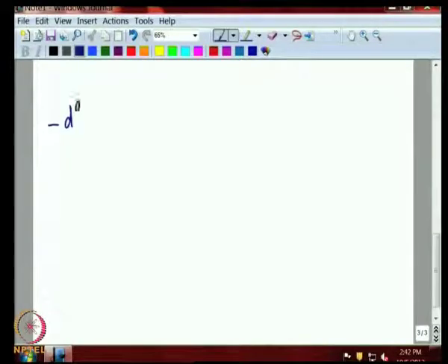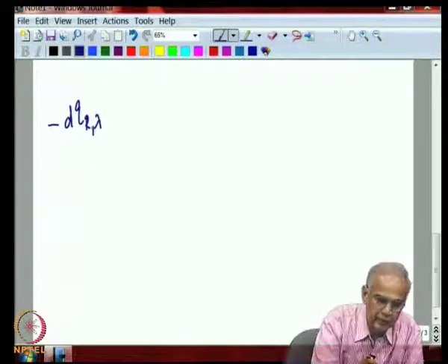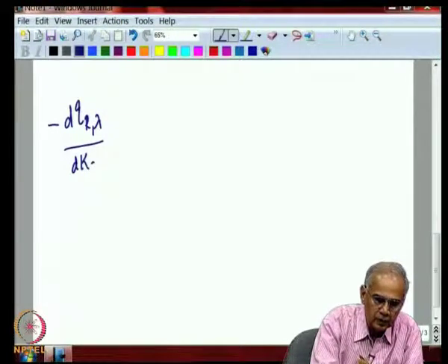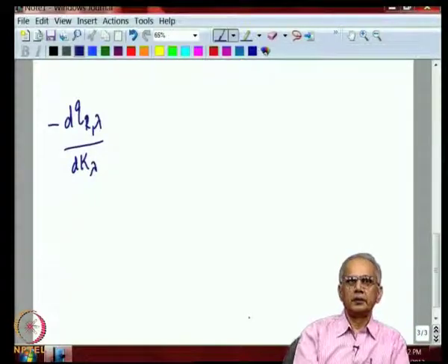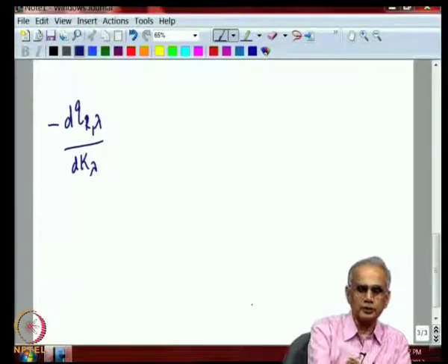So, that includes conduction, convection and radiation. So, ultimately we must know how the divergence of the radiative flux looks, and so we derive an expression. By differentiating this expression, we derive an expression for the divergence of the radiative flux, and for convenience we write it as minus. We write a minus because minus the divergence represents the energy added to the system.